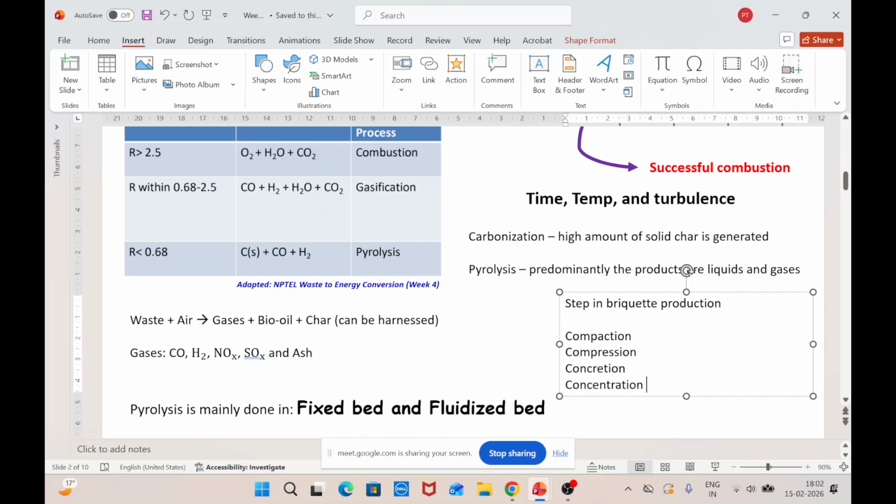However, in case of low pressure, you require a binder, because the pressure is going to be less than 5 megapascals. That pressure is typically very low, so interlocking may or may not be efficient. So if you use a low pressure compaction system, to make sure that the compaction process is efficient, you go for using some sort of binder.